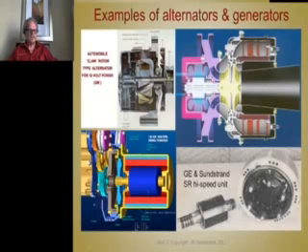Now this has to have slip rings to get the DC current in this coil. So that coil sets up a field around here, and to close the circuit, it has to jump across from North Pole to South Pole there, and that's where the flux linkage comes from. That goes from these poles into the stator. And as this is rotated by the engine and a belt, driven by the engine, that will cause three-phase AC to come off of this machine.